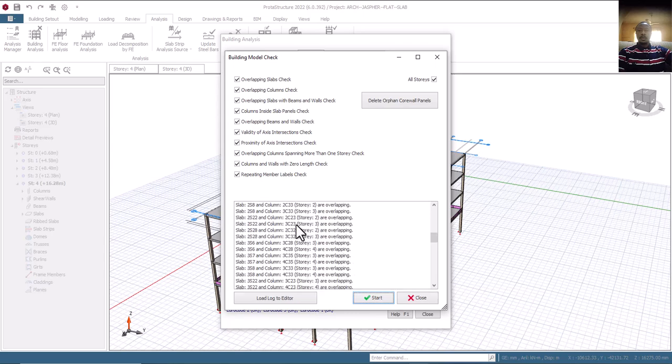So let's now see what those errors are. What are they talking about? If you look at all of them, they are talking about slab C's and column D's overlapping. Correct. Our slabs and columns are overlapping. Definitely you should expect that when it comes to flat slab, because of the way it's being modeled, we are talking of flat slab without column drop. Don't forget what we are dealing with is how to analyze flat slab and also solve those errors that come with analyzing flat slab. That's our area of concentration, and that's what we are going to deal with.